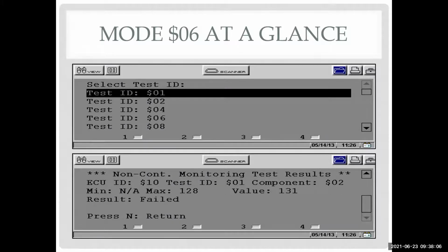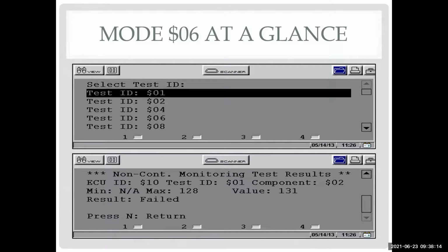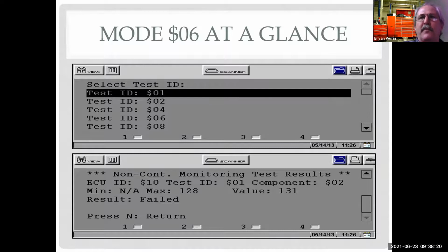And you said that's a 420 code? Yeah, 420 code: 420, 421, 430, 431. Those are all the cat efficiency codes. But the 420 is below, correct? Yeah, all 4 of those are for below efficiency. 420 is bank 1 converter below efficiency. 421 is bank 1 pre-converter, or warm-up catalyst, below efficiency. 430 is bank 2 converter below efficiency, and 431 is bank 2 warm-up converter below efficiency. So those are the 4 cat codes. They are all saying the same thing.